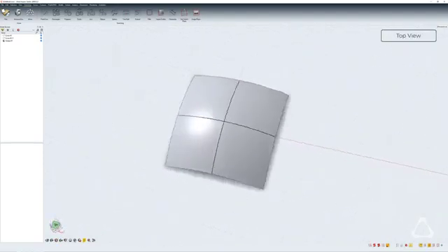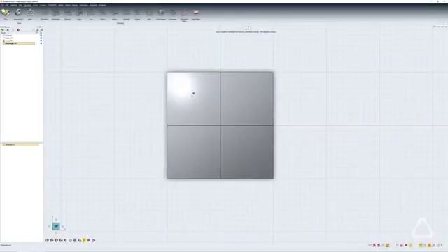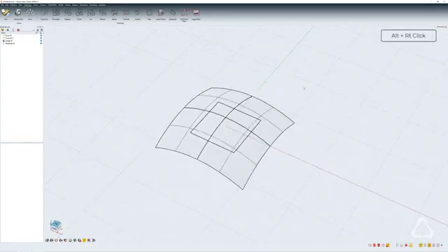In the top view I'm going to create a square or a rectangle and just draw it. Right click swipe, then move into the wireframe view using 1, and I just want to position this into the center. So double click on the rectangle, and by default it's pinned at the bottom left, so I can just click and drag these handles to make it a square. You could have also used shift when you were creating the rectangle to create a square. So alt right click and hit the home button.